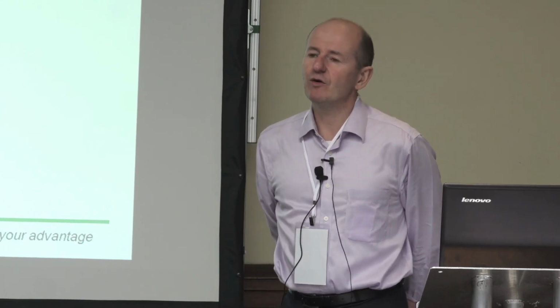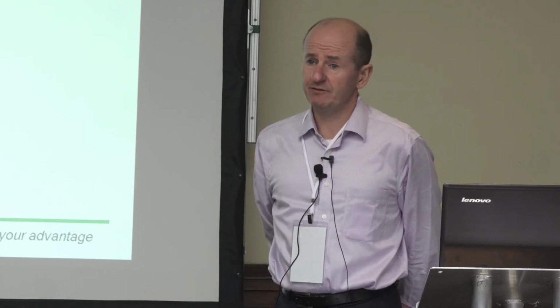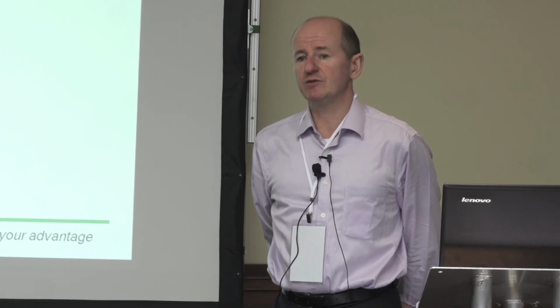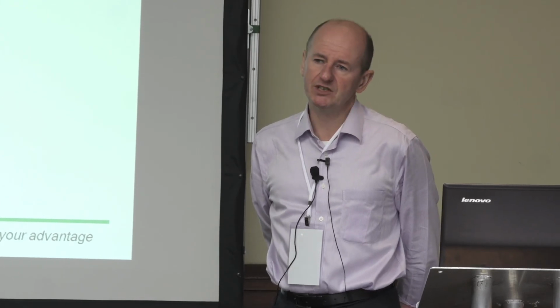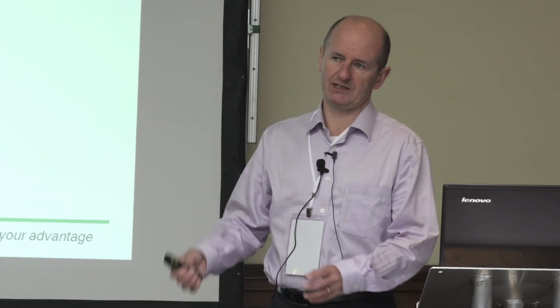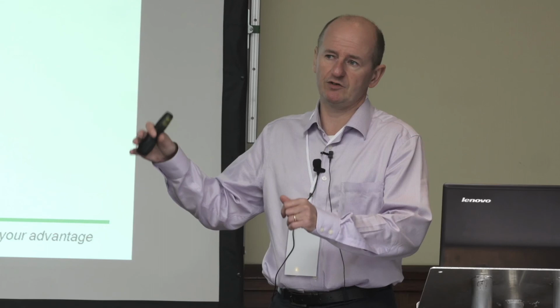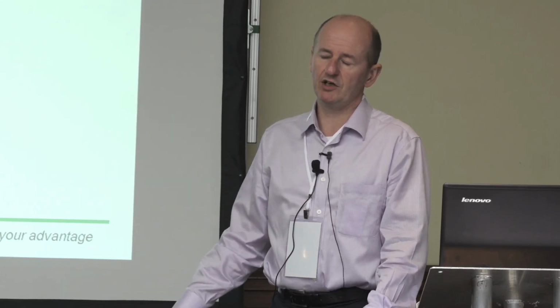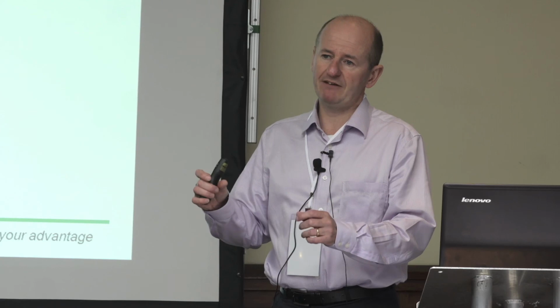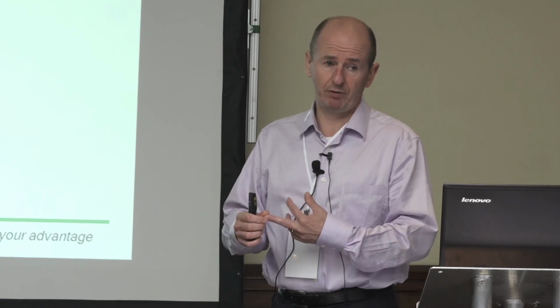I have an opinion on everything, Terry. Thanks for asking. Yeah. So GaN isn't fantastic for noise, but it's not a disaster either. So what people do with these LNAs, and they call them robust LNAs, and they're pretty nice parts, those Triquint parts. So you bias them at sort of 10 to 15 volts. The knee voltage in GaN is around about the 5 volt level, so you can't go too low. You bias them at 10, 15 volts rather than the 28 volts or even 40 volts you would for a PA. And the big benefit to them is that they can withstand a lot of input power.